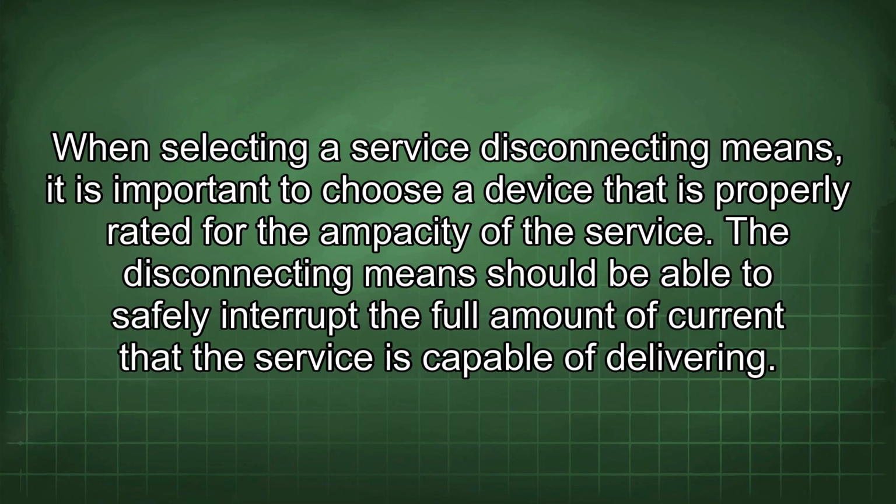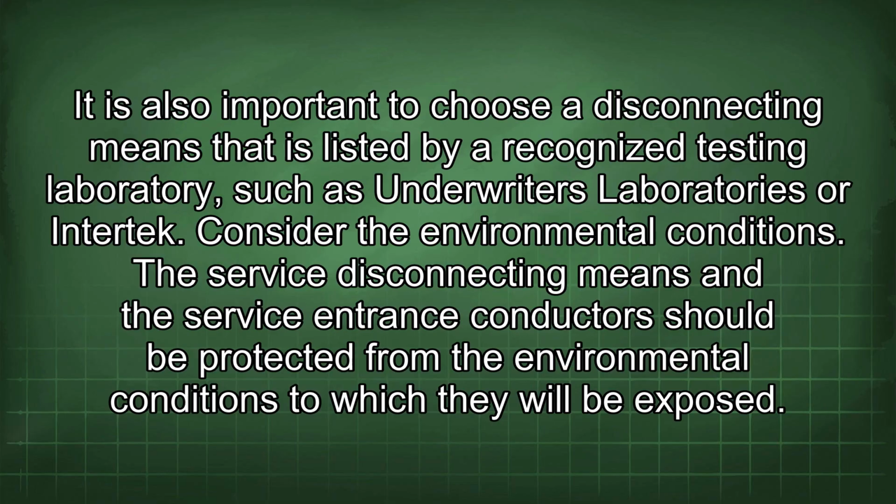When selecting a service disconnecting means, it is important to choose a device that is properly rated for the ampacity of the service. The disconnecting means should be able to safely interrupt the full amount of current that the service is capable of delivering. It is also important to choose a disconnecting means that is listed by a recognized testing laboratory, such as Underwriters Laboratories or Intertek.